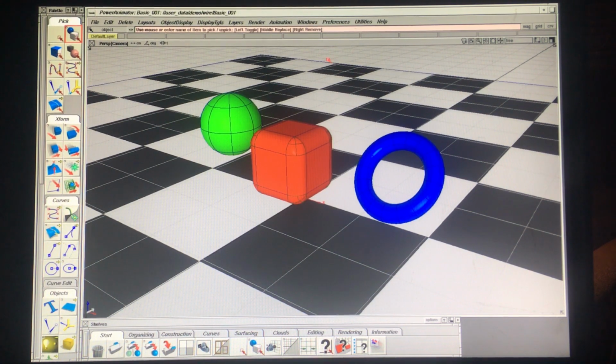I like that. So we know that we can set hotkeys. If you want to use these marking menus, you can, but then you can also set the hotkeys, Shift WER, to make this closer to Maya. All right, that's a good step.